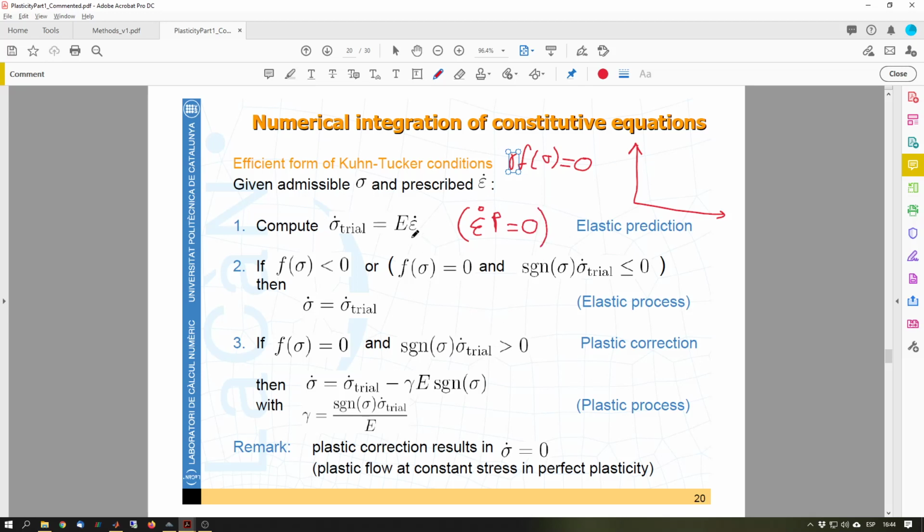So instead of the elastic strain rates, we are just including the total strain rates. So we predict that we are going to go, so we don't know where we are in our diagram, so we may be here or maybe here. So linear assumption maybe, or maybe we are at that point. So we are assuming that we go always elastically according to a slope of E. We don't know where we are.